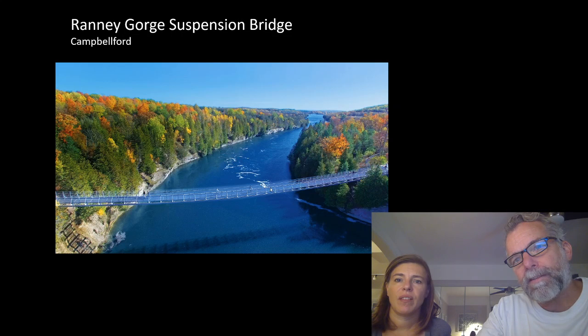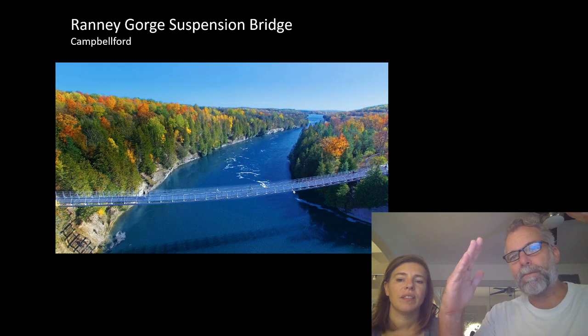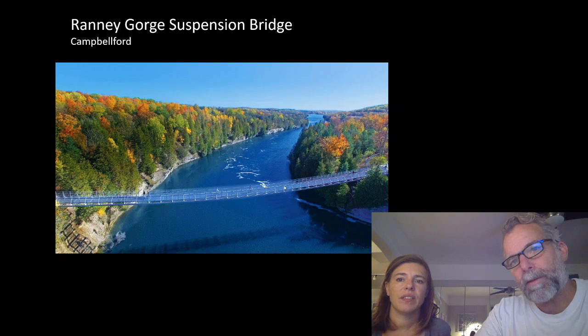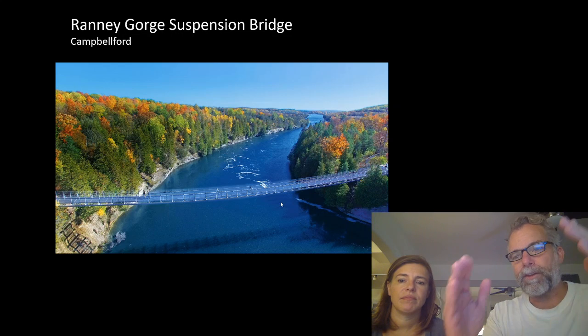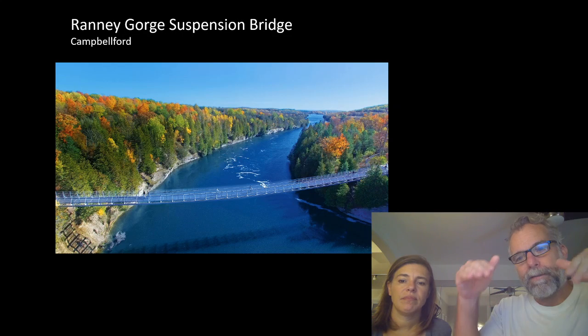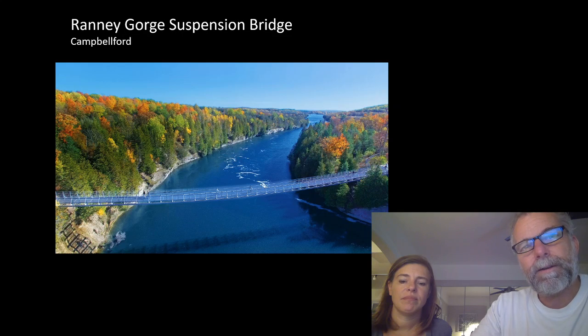You can see the crossing beams that pick up the grating stick out several feet with diagonal braces. That's to support the guard. So all of these things, which are kind of the visually dominant element in a way, are there for the guard, and not for the catenary itself.